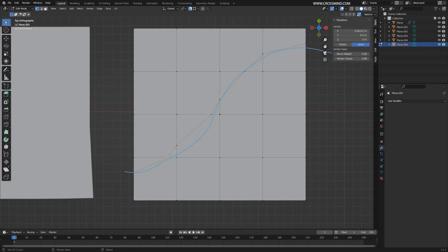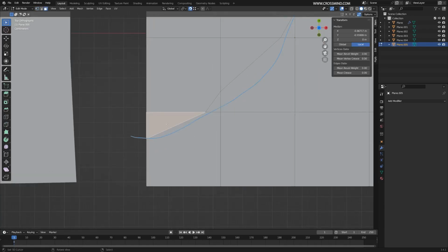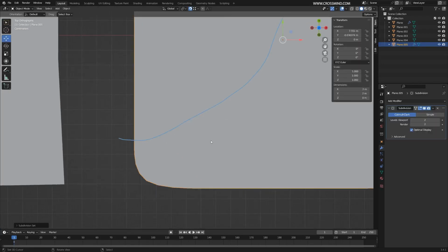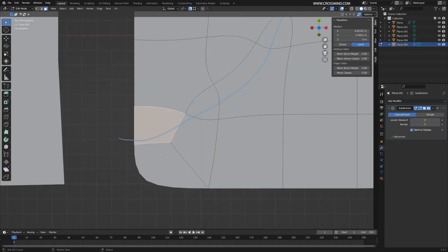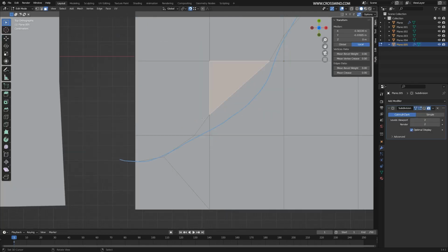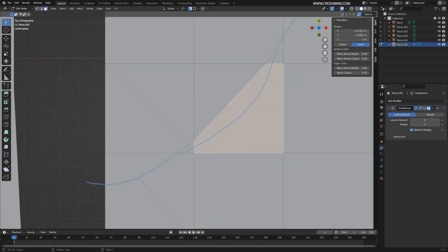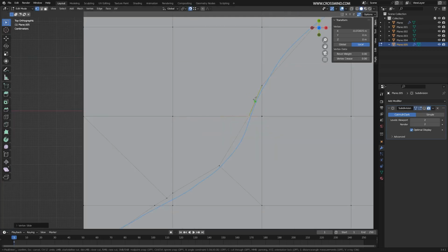So just take a cut tool. So in scenarios like this, where you have one triangle and one 5-sided, you can simply create a cut from here to here, and then you have 4-sided quads here. Let me apply smooth so that you can see the visualization. We have quads here, and these are nicely subdividing, but here triangles are struggling quite well to manage the flow. I'm going to create one cut here, similar situation. Now we have a quad here, and one quad here. So do the same thing, create a cut, and there you go. Then let's solve this one.